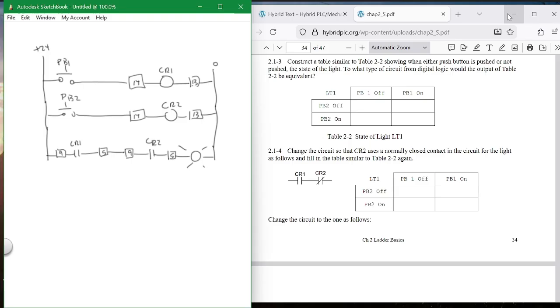And those relays are sitting there, and those push button stations are sitting there. Now, how do you get 24 volts? Any of the programmable controllers has a power supply right by them with 24 volt power supplies. They're all there. So don't tie to the 110. Stay away. But the 24 volts that goes over to the PLC, you've got a plus 24 and a 0. The red is the 24, the 0 is the black wire. It will work with any color wire that you want, but we typically use red for the power and black for the neutral, although anyway, that's what we've typically done.